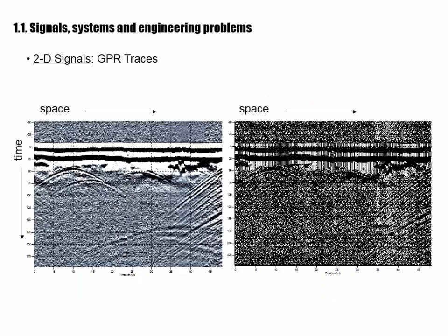And if we do this kind of measurement along a line, along the space, the x-axis, or the y-axis, or z-axis, then it gives you a two-dimensional signal. And this is an example of a GPR trace, so that you have a dolly with the electromagnetic propagation and receiving system, and you just roll it along the line that you want to scan, right?